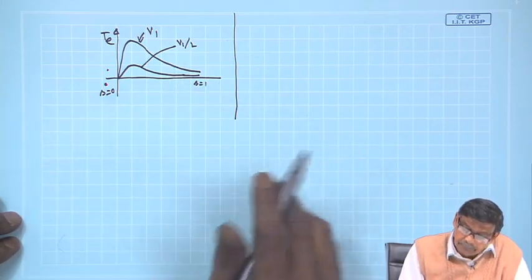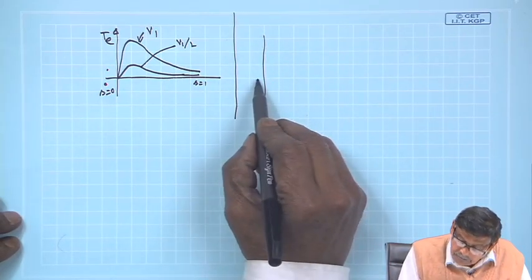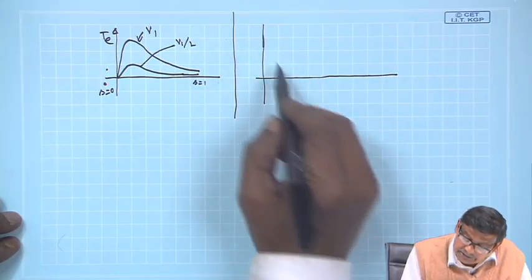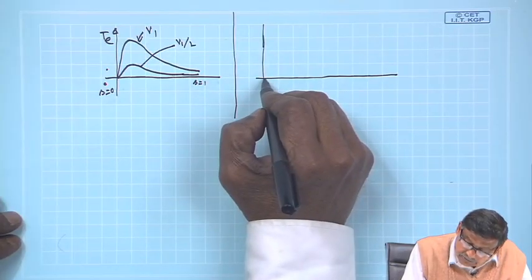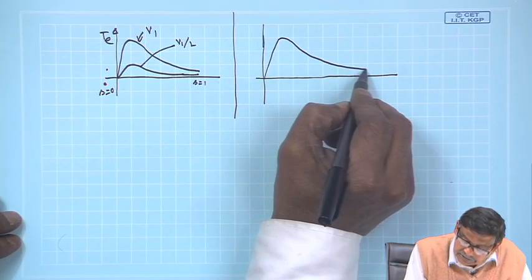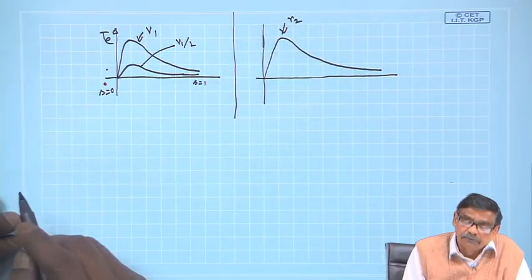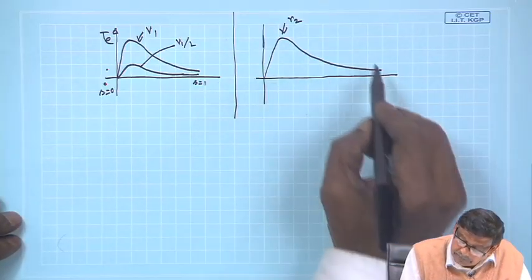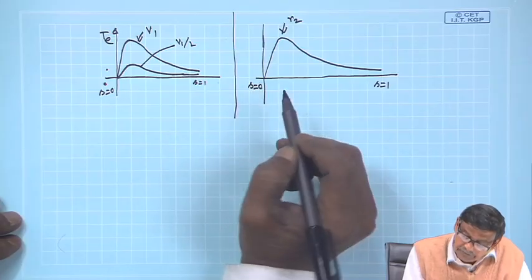Then we discussed what happens if the rotor resistance varies. If rotor resistance is varied, how does the torque slip characteristics change? Suppose this is the torque slip characteristics with the inherent rotor resistance R2 dashed with a constant multiplied. This is S equal to 1, this is S equal to 0.